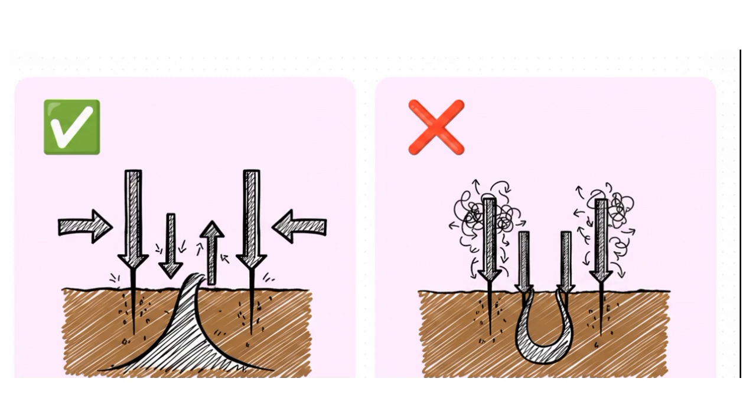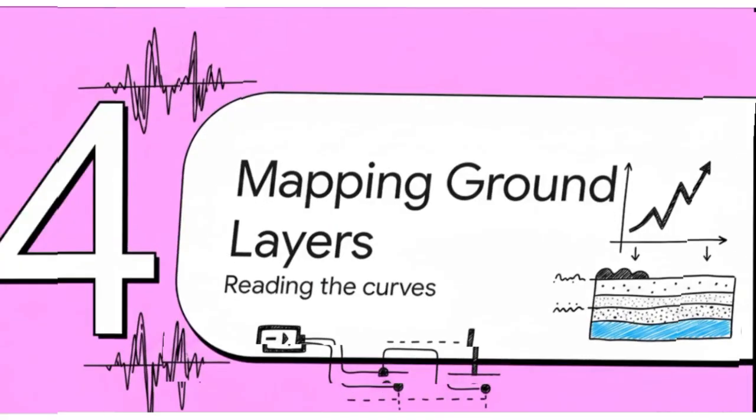Second, it's actually more accurate. Keeping those inner electrodes fixed helps you spot random near-surface errors in your data. And finally, despite some mathematical confusion you'll occasionally hear out in the field, side-by-side comparisons prove the Schlumberger Array actually has a slightly deeper effective depth of investigation than the Wenner Array. It just works better.